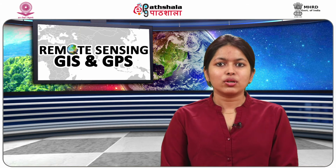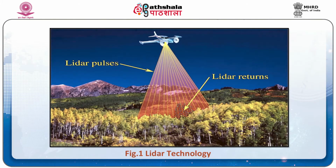With the latest technologies, it is also possible to obtain color values of the scanned surface to create automatically textured models. LIDAR is ideal when high accuracy measurements are required and is very cost effective for the amount of data generated. Airborne LIDAR is becoming more and more popular as a source of terrain mapping due to the high level of detail it provides, as shown in figure number 1.